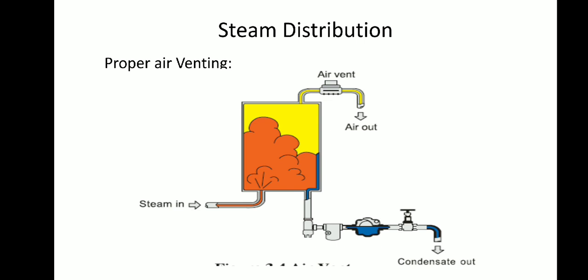The automatic air vents for a steam system should be fitted above the condensate level so that only air or steam-air mixtures can reach them. The best location for them is at the end of the steam mains as shown in the figure.